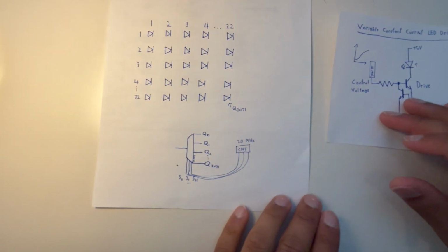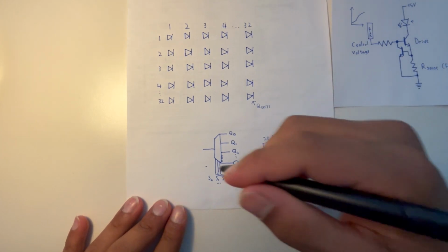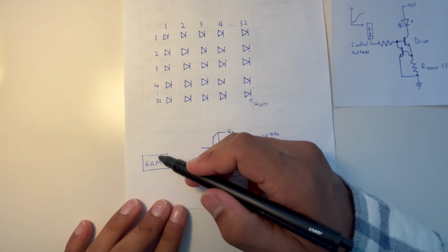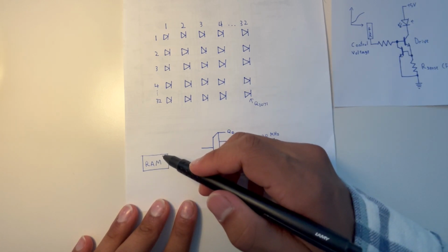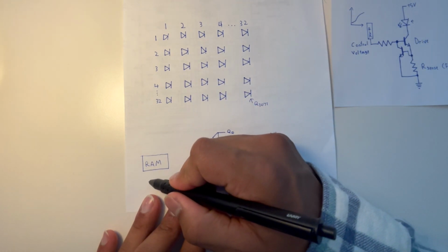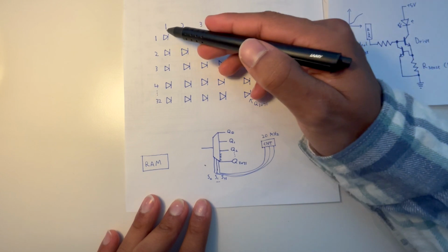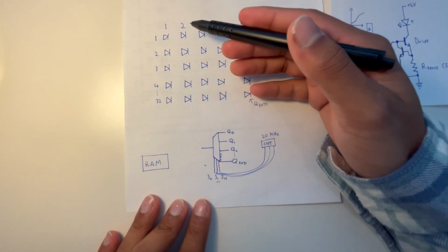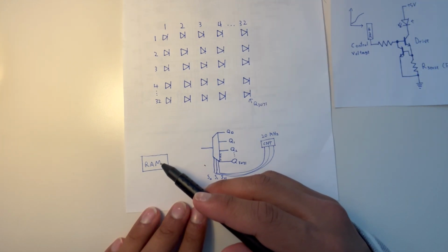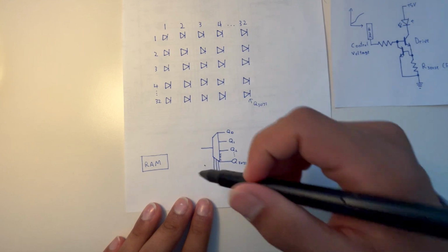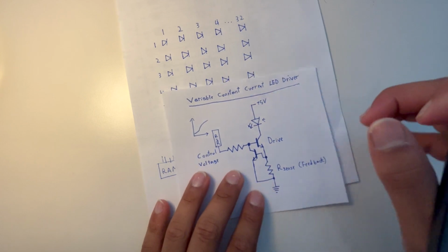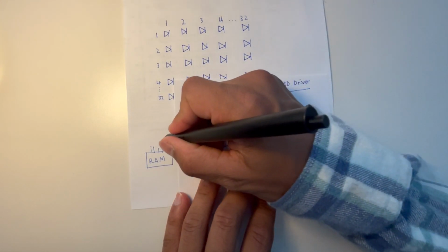Now the last consideration is where the brightness data comes from. And for that, the matrix uses a RAM chip. So for this, the brightness of each LED is stored in the chip in the order that it's going to be accessed. So in address 0, when all the address pins have a 0, the brightness for LED 0 is stored. Then in address 1, the brightness for LED 1 is stored, and so on, all the way up to LED 3071. Since the brightnesses are stored as binary values in the chip, it makes it quite easy to display. The output of the RAM chip goes directly to the R2R ladder in the constant current source.